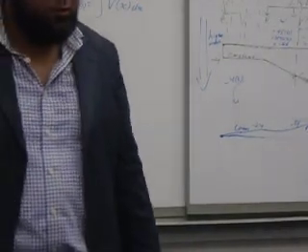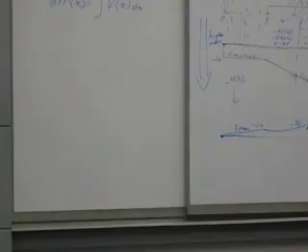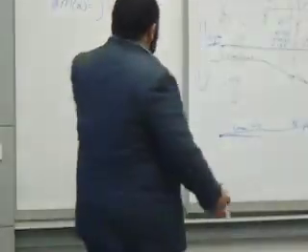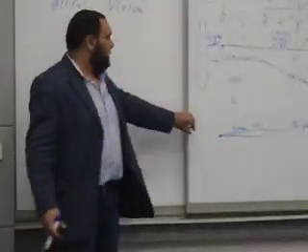The bending moment is the integral of the shear force. And actually the shear force is the integral of the load. Now we are increasing in the order. This is why it's higher order. Let's do a check to know this relationship.